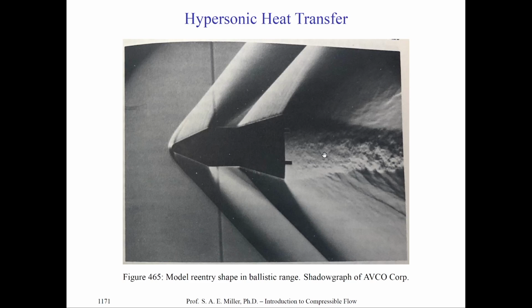Here we can see a large turbulent wake. We see the vehicle itself is in black, and we have a reference line of where it's taken with respect to the camera. Here we see the blunt leading edge, which you can see is indeed a constant radius of curvature. There are particularly strong oblique shock waves coming off the vehicle.